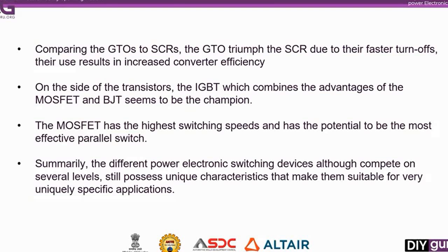However, GTOs require a snubber to operate normally, and snubbers for high power applications are quite expensive. So the high on-state voltage drop in GTOs, coupled with the high gate current requirement and the high losses in the gate drive, are quite a number of demerits for the GTO. The MCT seems to be an improved GTO, seeing it has a lower forward voltage drop, a higher current density, and an improved gate technology, hence making it easy to control.